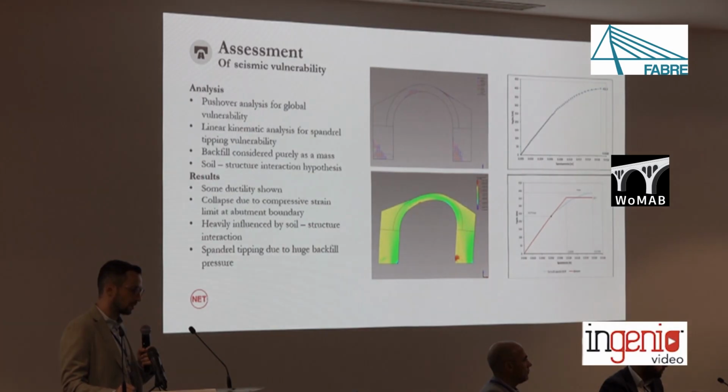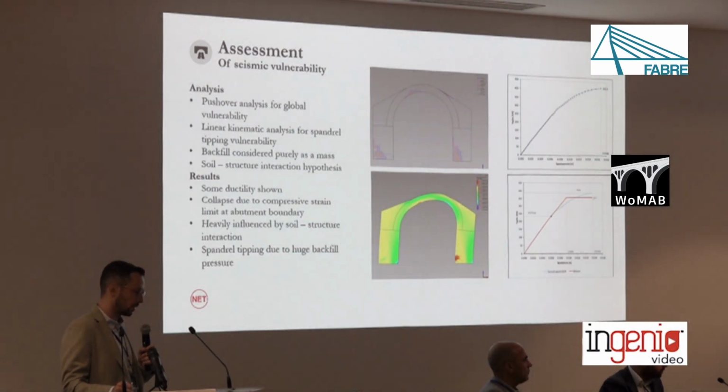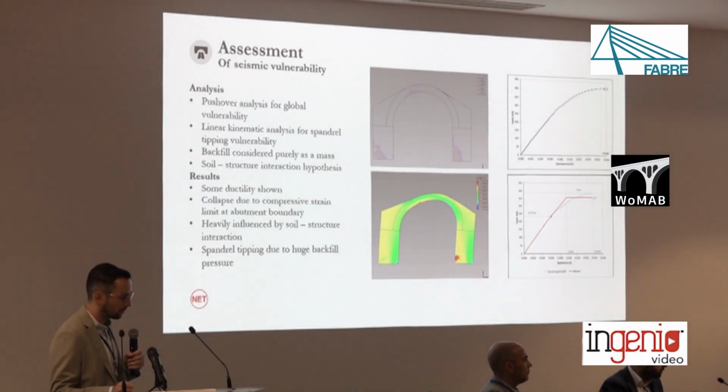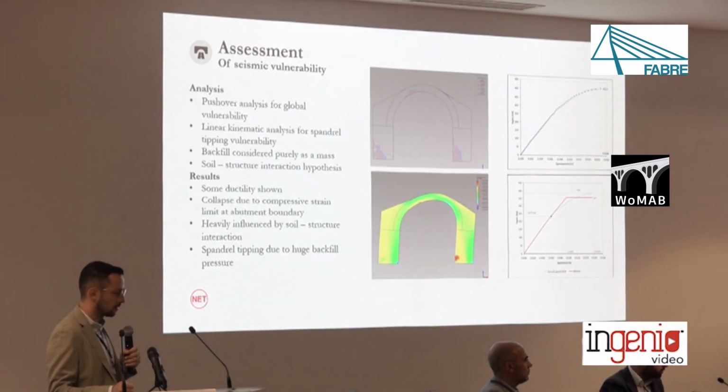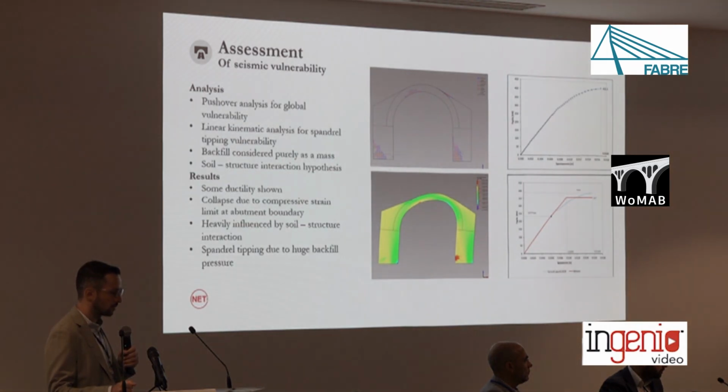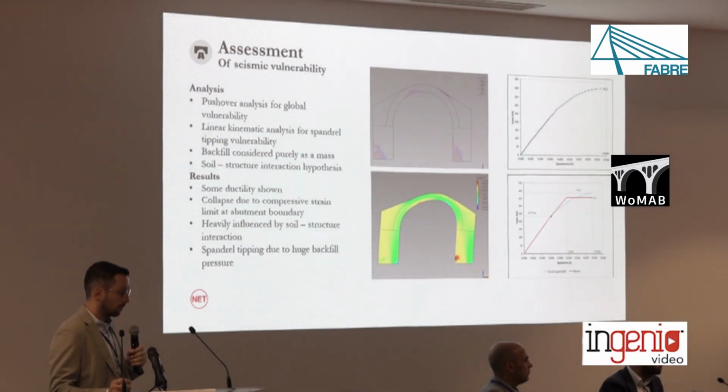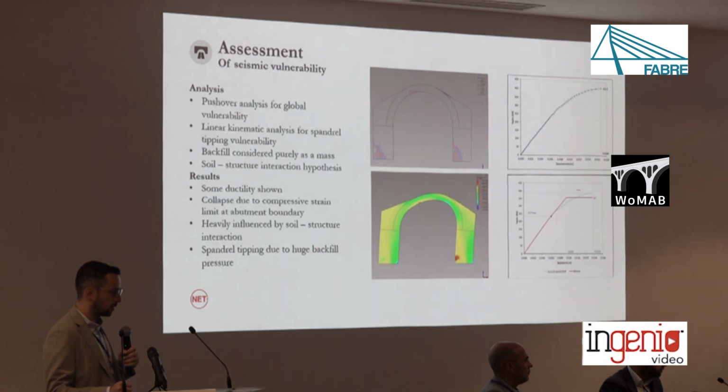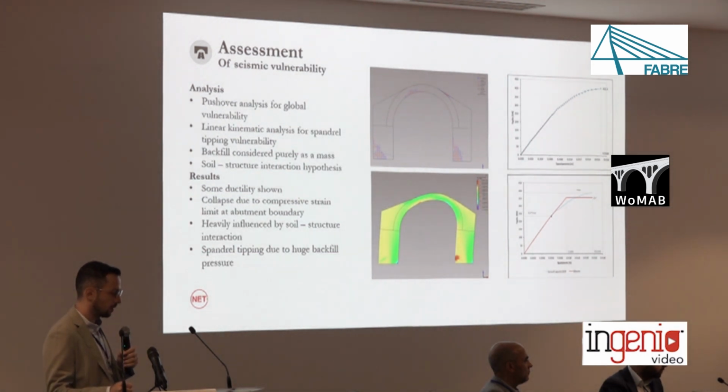For this particular structure, it was agreed upon a typical approach, which is the complete restraint, maybe 1 meter under the walking plane of the road passing through, to account for the terrain contributing to the restraint of the structure. For sure, this will have quite the importance in the results.